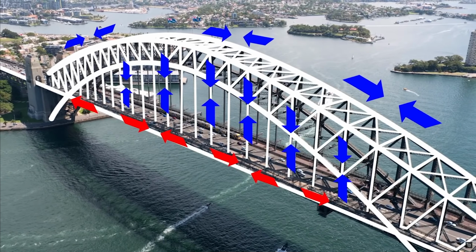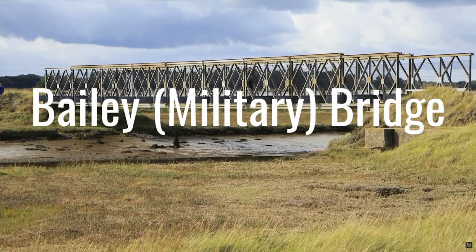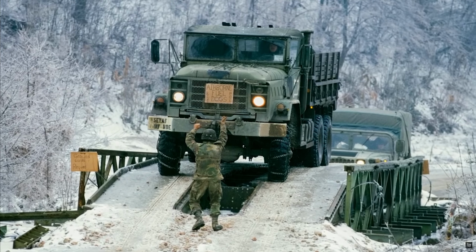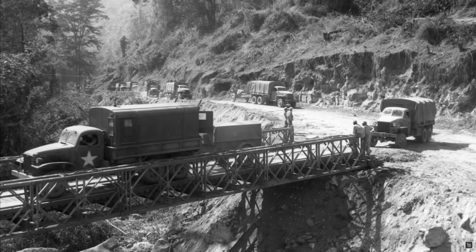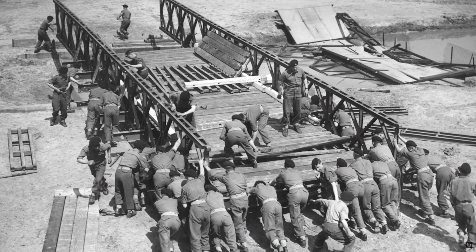Aren't truss bridges used by the military for rapid deployment? Absolutely. The Bailey Bridge is a military bridge that is prefabricated, pre-built away from the site where it is to be put in place to transfer vehicular or pedestrian traffic. It really came out of the need for military units to be able to quickly build a bridge, light enough for them to carry with them as they move from one place to the other. And it's sort of like an erector set, piece by piece, prefabricated, put together, and can be constructed without heavy machinery, without a crane or any pile drivers of any sort.